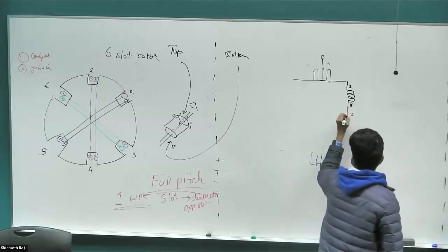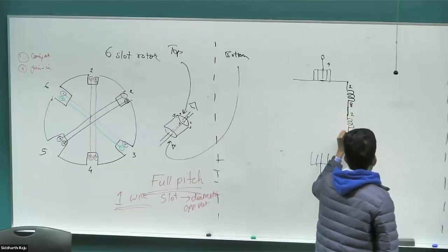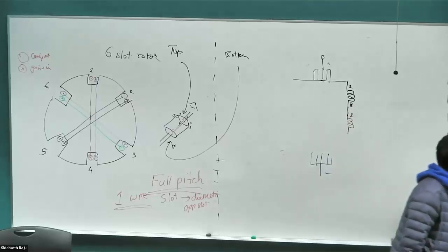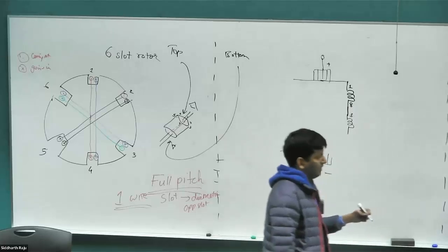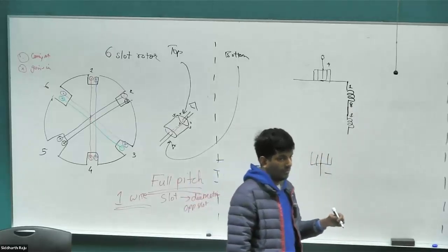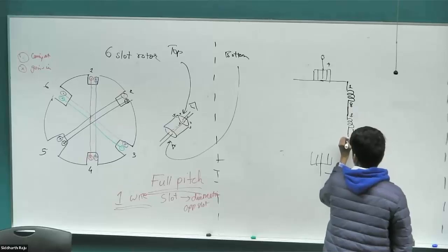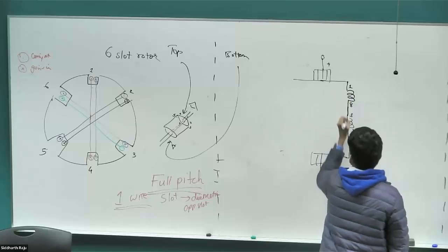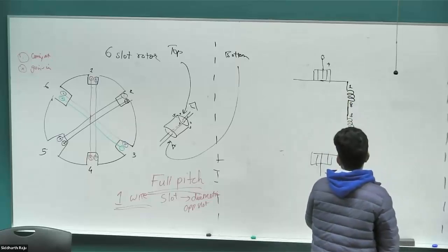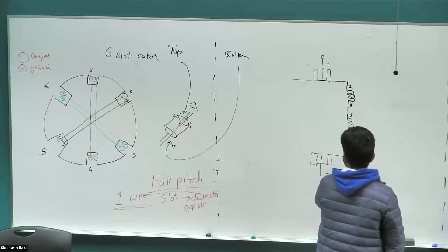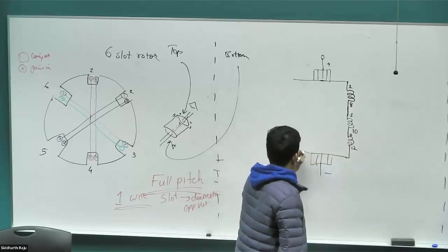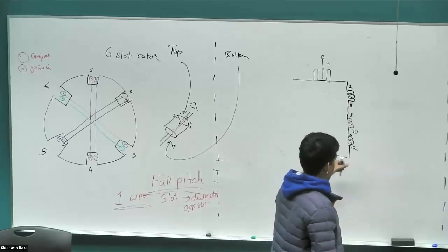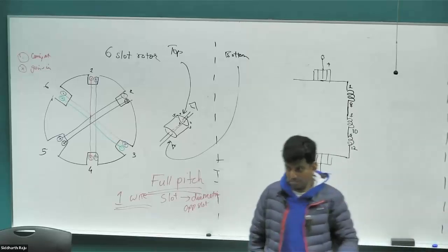2. Thank you. And then 2 becomes conductor 3, slot number 2. So it goes to conductor 3, right? And then conductor 3 becomes 10. Perfect. And then the other one is straightforward: it goes up by 2, so 10 goes to 5. And then I'm assuming 5 goes to 12. If I'm wrong, do let me know. Okay, so that is one parallel path. And then 12 comes back and terminates on the second commutator.